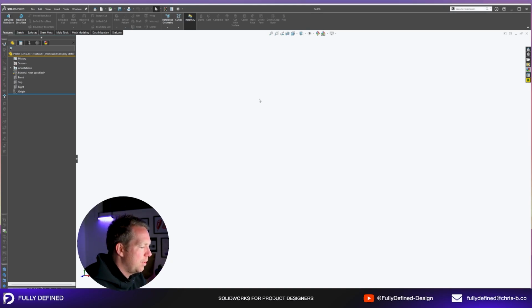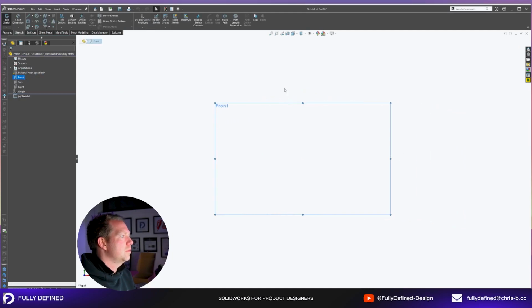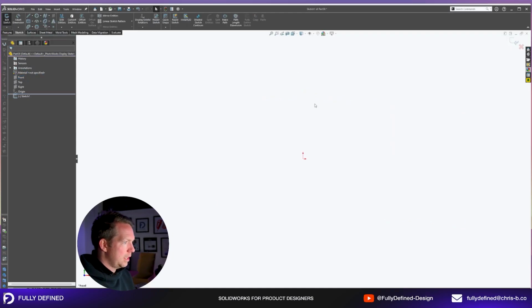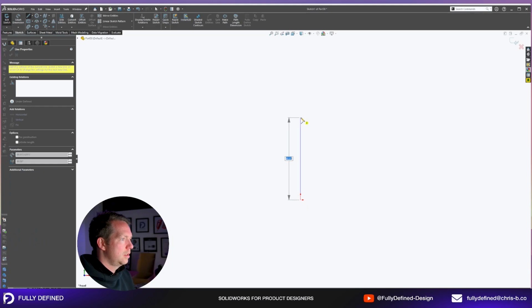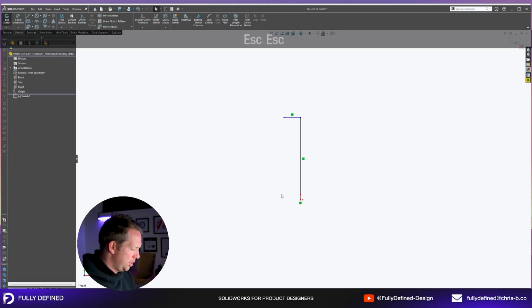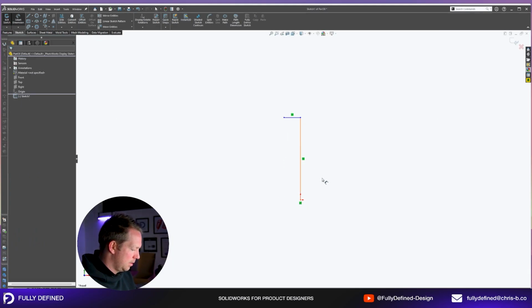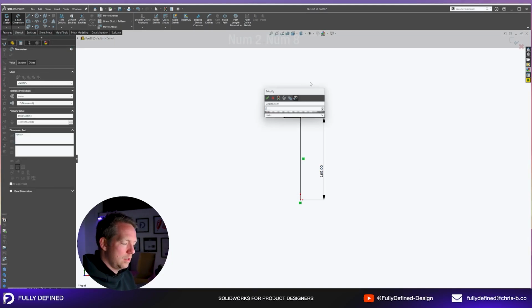Now, I do have the box instruction card here, or info card, which has the sizes of each of these hex keys. And I'm going to be referring to this with what I'm sketching on the screen. So we're starting with M5, and it says M5 is 28 by 160 millimeters. So let's do this on the front plane, and I'm going to create a very simple sketch, straight up and to the left. And I'm going to dimension it 160 by 28 millimeters.